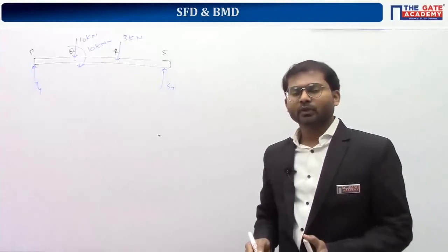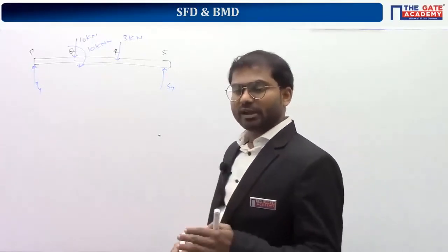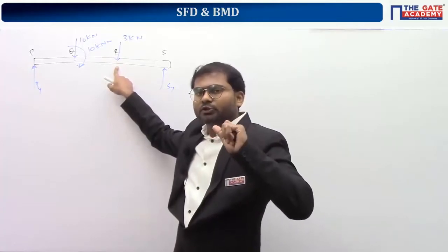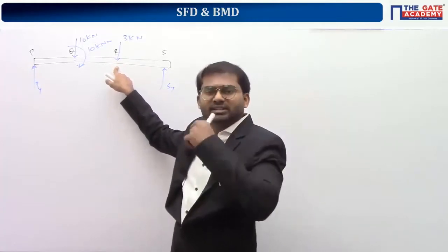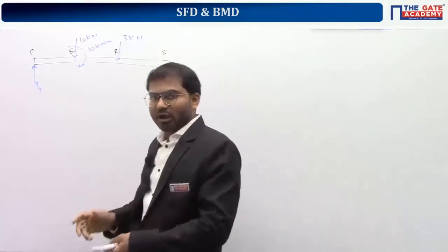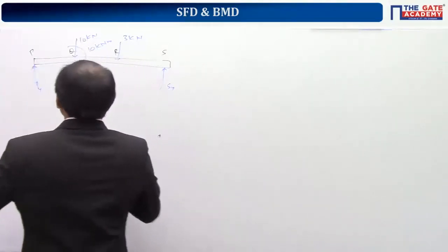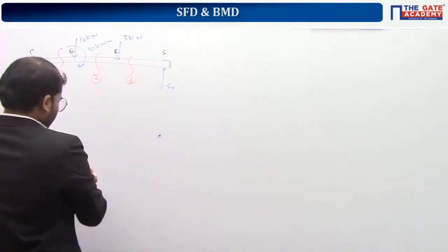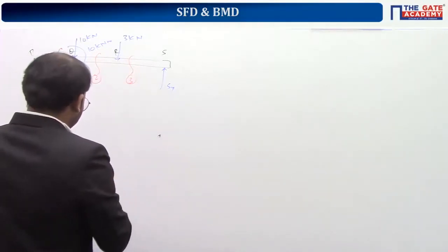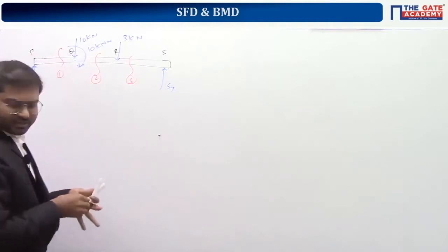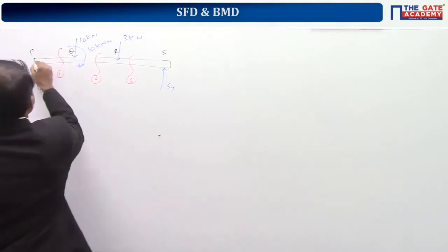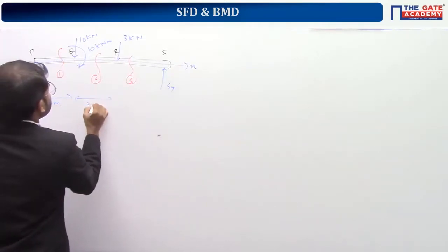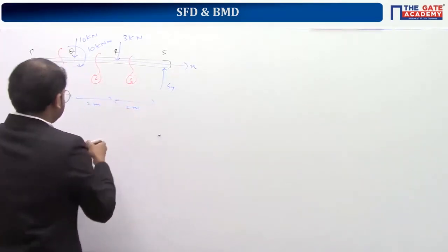That's very easy. Now in this question, they're expecting us to get the value of bending moment at the location R. At this location they're asking. So here you can eliminate many unnecessary steps, because if you have to draw the whole bending moment diagram, you should do cutting thrice. So the left part of the first cut, if you take the dimensions, this is the x-axis, this is 2 meter, this is another 2 meter, it is another 2 meter.